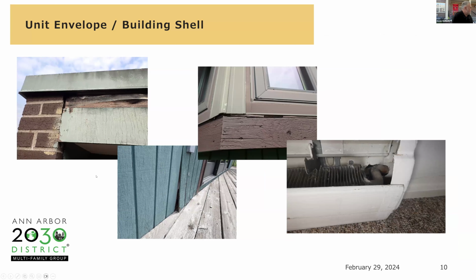As you're going around doing routine maintenance on buildings, just keep an eye out. Here it's up high, but we still get air leakage. Now this is going to come in through the ceiling assembly. We need to repair this, and it's gotten some pretty significant water damage. That's not complicated, but you're going to have to get a trim carpenter or sider or someone in to repair the water damage first.